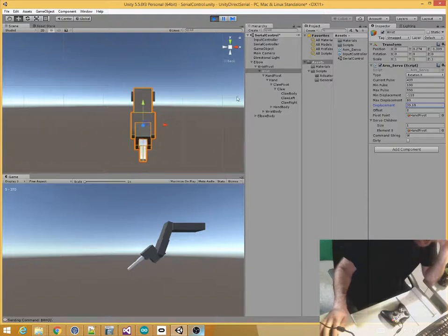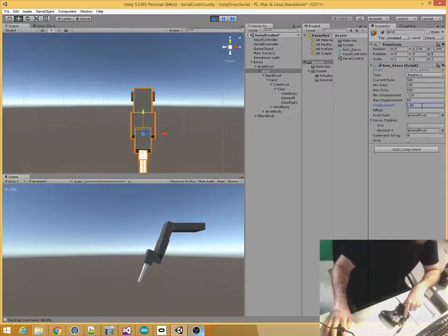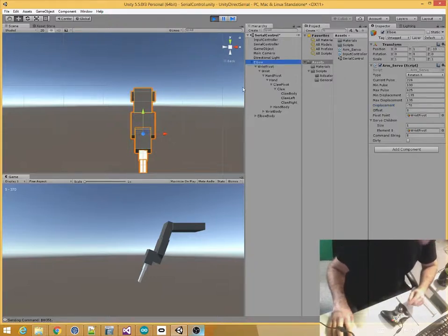So what I want to do is read the input from the Xbox controller, read one input at a time for each input that I want to map to the position of the servo, and I want each different input to affect a different element of the hand, so one of these to point to a different script.